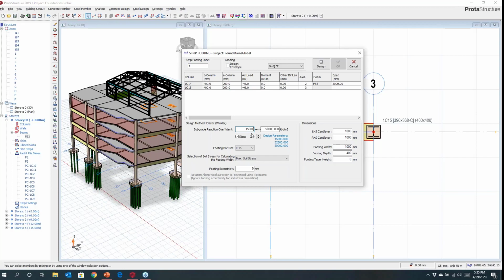Or if you're very comfortable with the geotechnical spring parameters, then you could just use a fixed amount. Now, you can have slightly eccentric footings if you wish. You can also take advantage of tapering, and the tapering can occur both in the strip footings here, or maybe within a pile cap, or even a pad base. So you can define tapers in here.